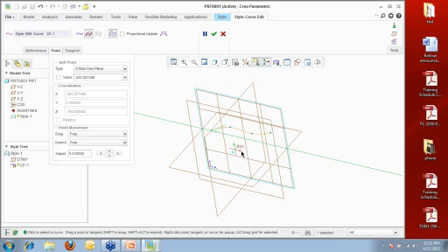So in an x coordinate from this, it's negative x, it's at 202. In z, it's a specific distance that I have right here. So again, even though ISDX has the idea of just push and pull and kind of move things around, I can actually set values to points that I want to change. So we'll go ahead and leave this curve alone, okay?